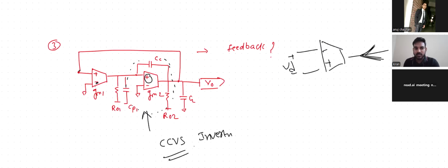If it is going outside, then what can the problem be? Cannot you check the feedback here? If you are breaking the loop somewhere and you are increasing the voltage like that, you can check. It is not fixed that I want inside current or outside current. But you can break the loop anytime and add it in place, and you can see whether all the loops inside the system are negative feedback loops or not.